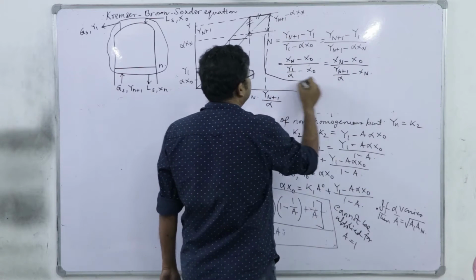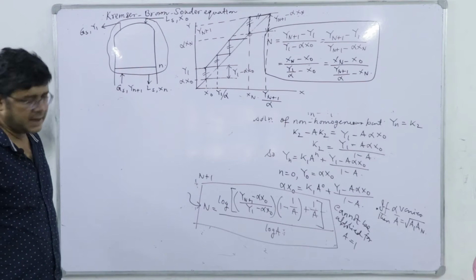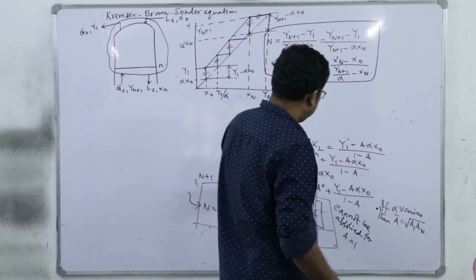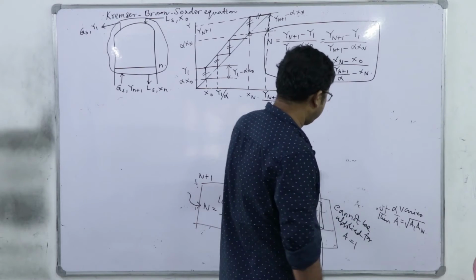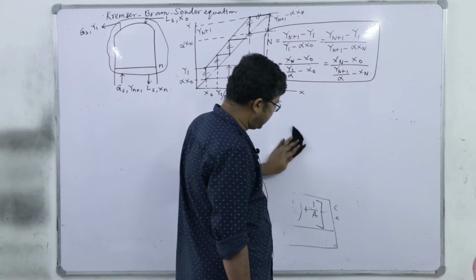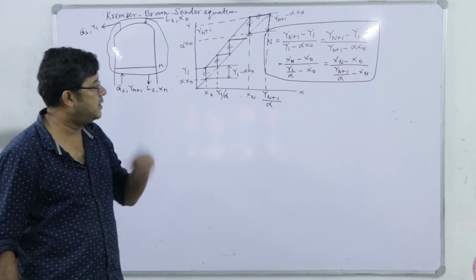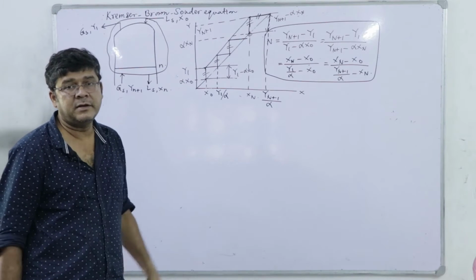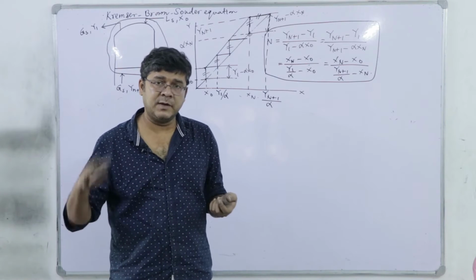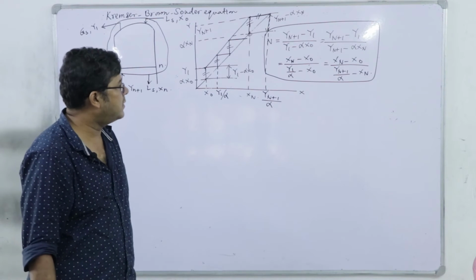So, there are 4 expressions in case of parallel operating and equilibrium lines. So, these are the very basic analytical ideas about the solution regarding the number of stages. First, we have used the staircase, that is a graphical technique. We can also go by an analytical technique, but there is a stage-wise calculation. We can write a code. If you wish, you can write a code with a for loop in C, and it will go on calculating, and there will be an if statement where we have to check whether yn, small n, is greater than y capital N plus 1, that is the inlet gas composition, and there it will stop and generate the required number of stages. So, you can write a code.